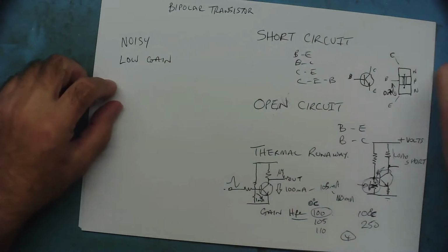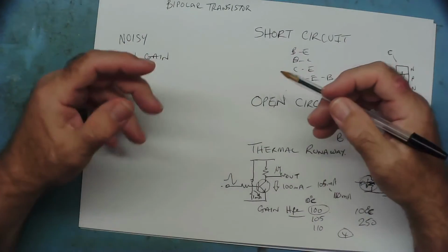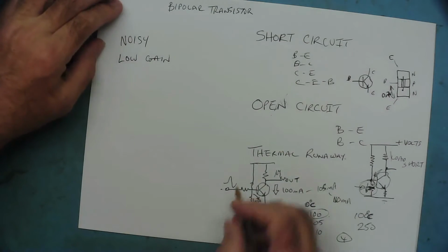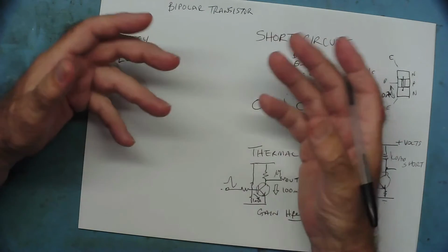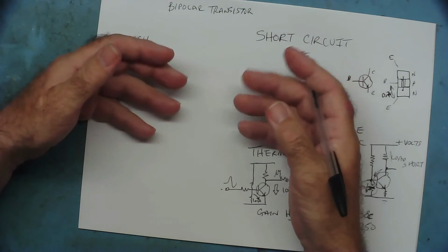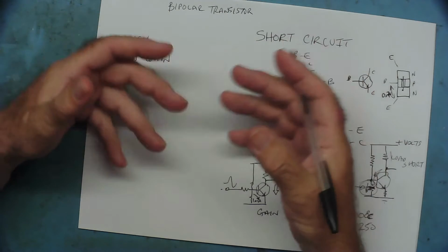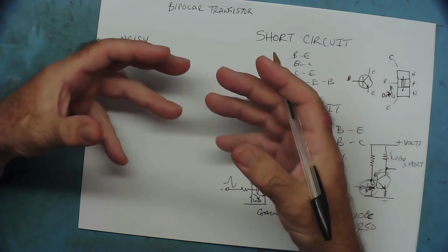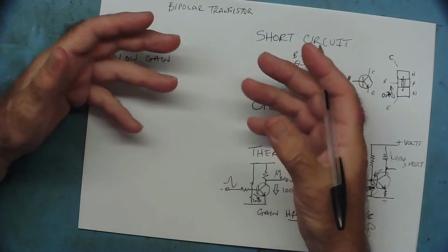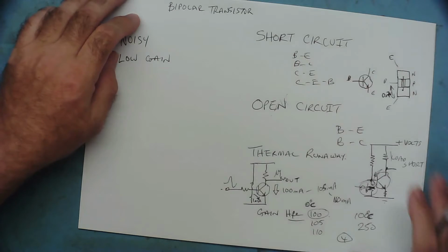I will just mention, by the way, before we turn the page, I often have another thought. Transistors, when they fail, there's 2 other things you really should know about. Quite often, when a transistor fails, it can do it quite spectacularly. They can set on fire, they can explode, they can literally just detonate. Often you can see, especially on large power transistors, a chunk missing out of it. So they can fail quite visibly and quite spectacularly.